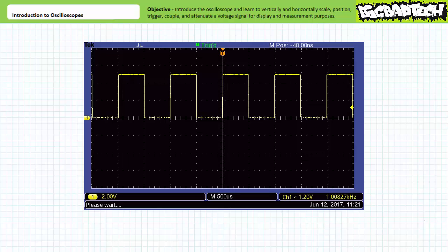As long as the triggering event regularly occurs, the oscilloscope regularly samples the waveform and spits out data. For our sample test waveform, triggering at 1.2 volts going positive would mean the oscilloscope establishes roughly the first quarter of the rising edge of our pulse as our one beat. Every time the score hits the one beat, the oscilloscope captures the window of data and displays it on the screen. Given our waveform is periodic or repetitive in nature, establishing a particular one beat isn't all that important.